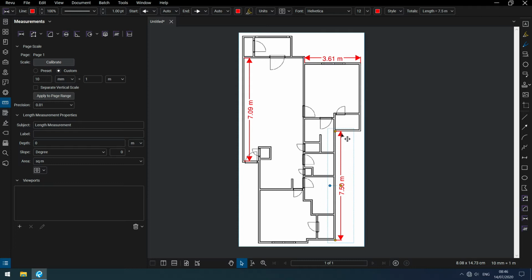When you've done your measurements, or after doing your measurements, now I've got it right, after doing your measurements, you can select each single one of them and select a few different options regarding color or thickness of lines, or if you want to have those little arrows on both sides or not, and you do all that in 2 different places. First and easily reachable place is the properties bar, the dynamic properties bar here on top.